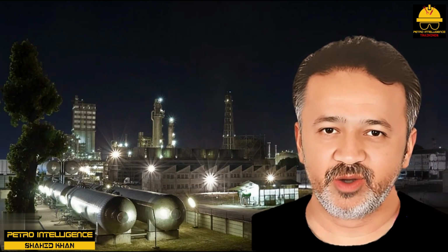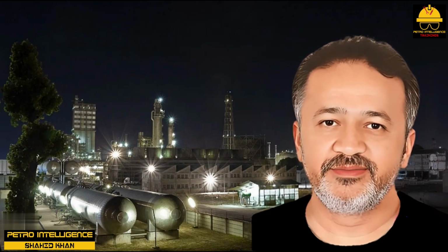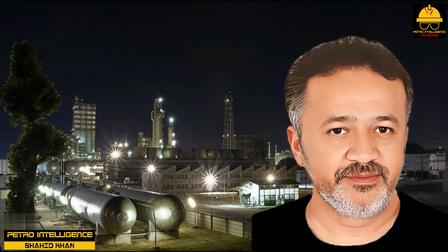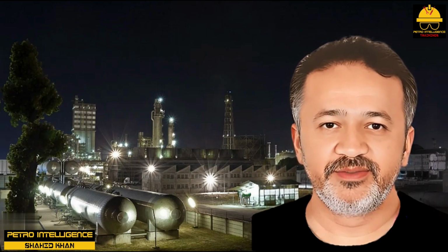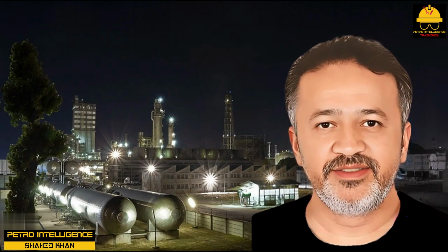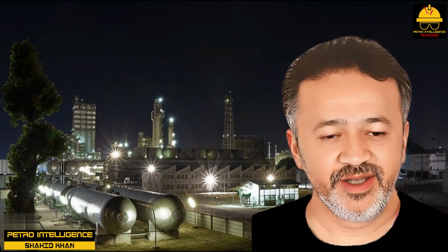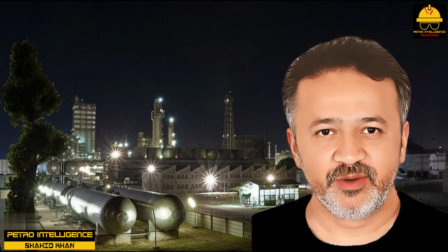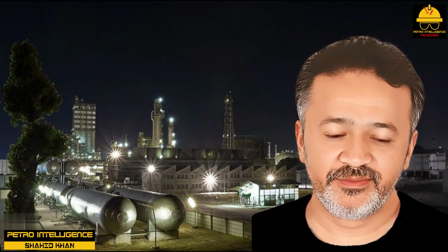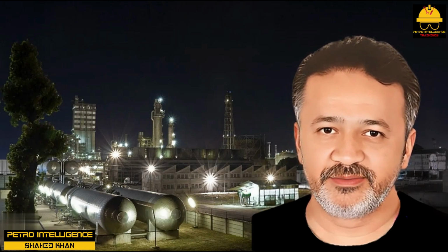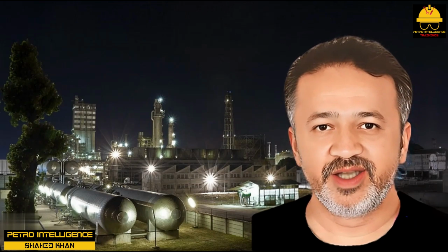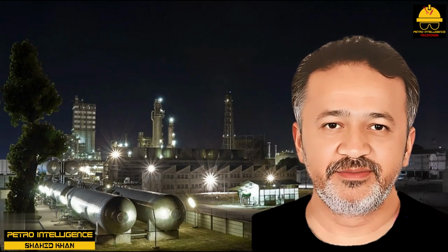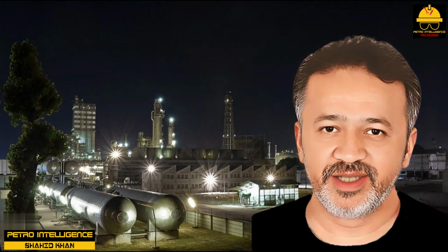Polymerization. This is an old process using a solid bed of phosphoric acid. Reaction takes place in the vapor phase. Feed is normally propylene. Products are hexane and nonane. Polymerization is a very exothermic process. There is another sort of polymerization process used to produce viscous polypropylene. The reactor is a refrigerated kettle evaporator where the reaction takes place in the liquid phase. The catalyst was isopropyl chloride. The polypropylene product was used by Texaco in the 1960s as an engine top cylinder lubricant, added to gasoline at 1 cc per gallon. The polypropylene is made at the refinery.